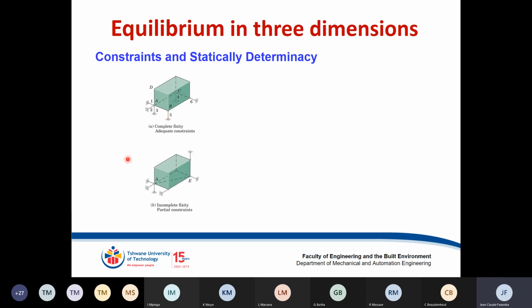Position 2, let's try to test it as well. In terms of Y or Z axis, I've got 2 restrictions. This one here and the one in the corner. Will that be enough? That should be my next question. Because if you check, your block will have a tendency of swerving each side.